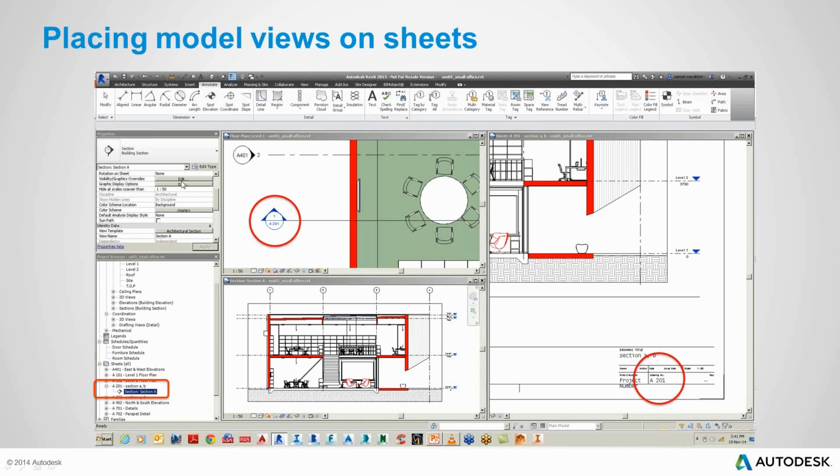So when you first go into a section, the section marker is not going to give you an alphanumeric number. It's going to be blank. Only when you place that section on the sheet and you give it a drawing number will that section call-out be populated. And of course, as projects push and pull, we have more sections, or we need to reorder our drawing numbers. When we change it on the sheet, it's going to update it in that section view. So there's some really cool intelligence here that's going to save you a bit of time when you're doing your documentation for your print output.